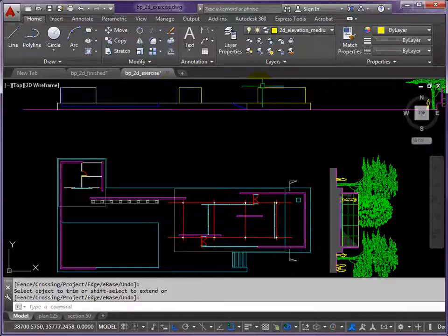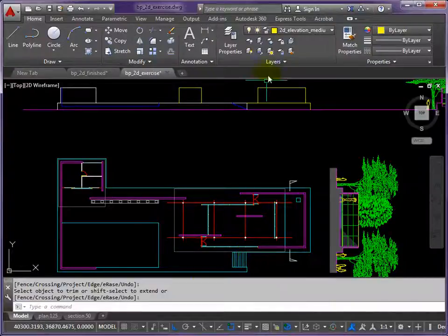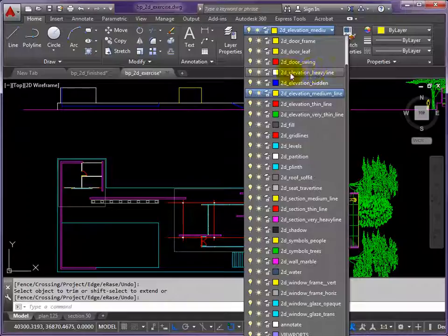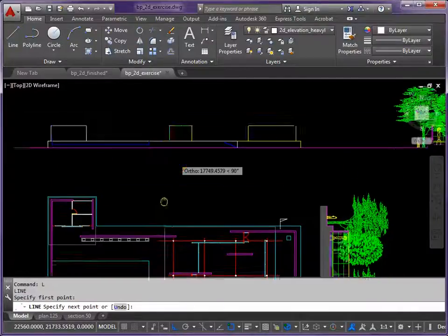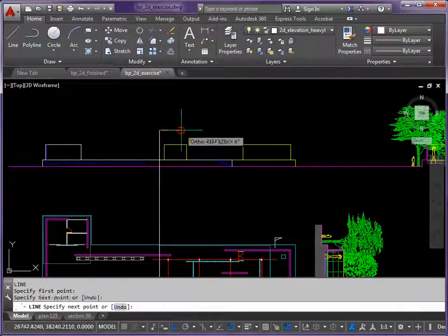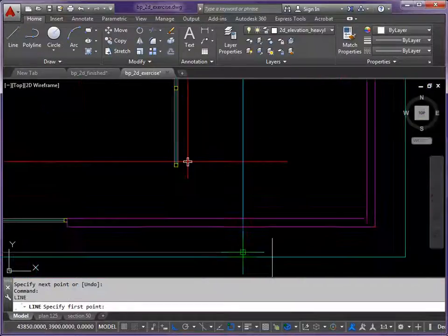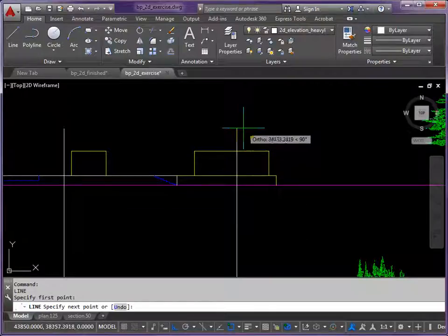Okay, sitting above these is a portion of roof. So I think we'll stick the roof on first. So I'm going to go back to the white layer now, to the heavy line layer, 2D elevation heavy line, and we'll bring a line up from the roof up past the objects, and this is where the roof starts on this side. So we'll just bring it up.